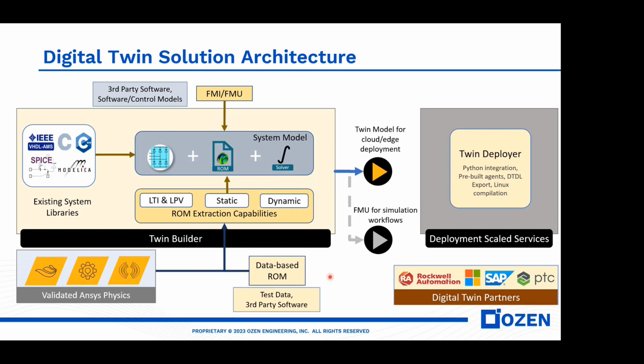So when you extract a reduced order model, a GB-sized case and data file, which is probably 2 GBs, will be extracted into something which is a couple of KBs. You are not capturing, to give you an example with respect to physics, the turbulence parameter at every cell location, or the temperature at every cell location. You're just capturing one out of them.